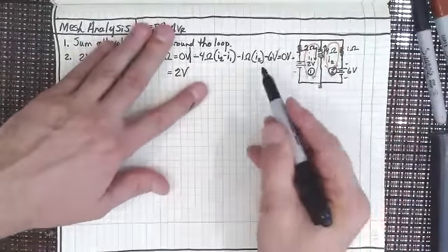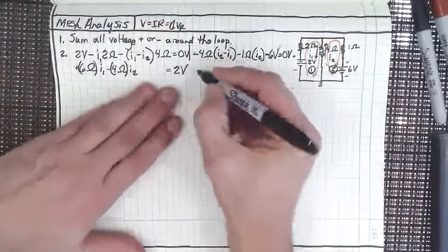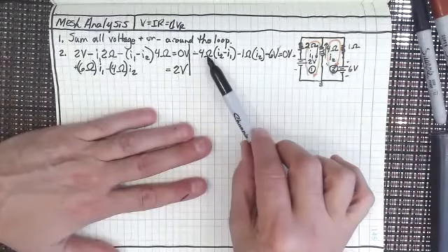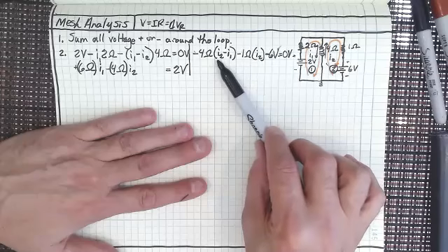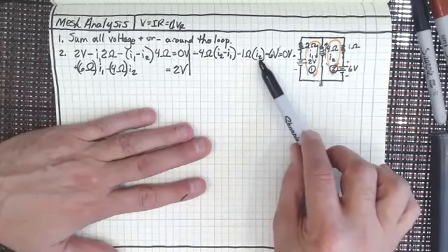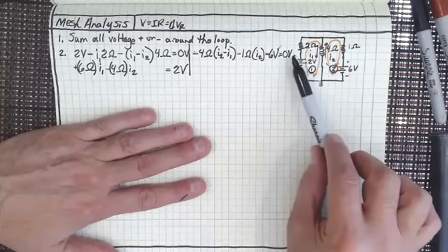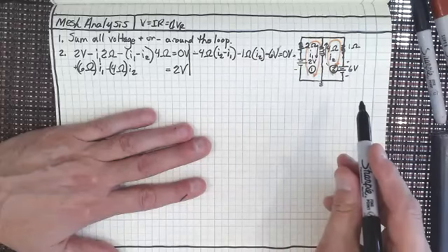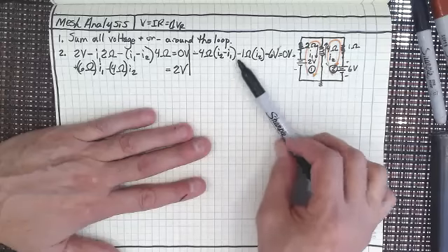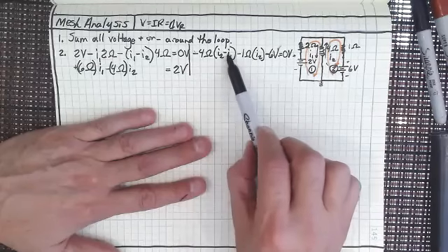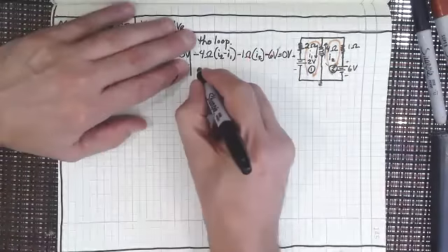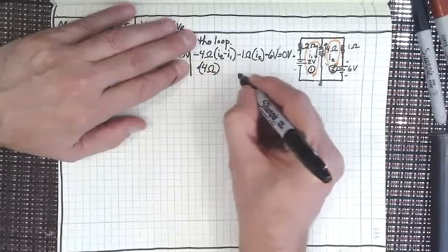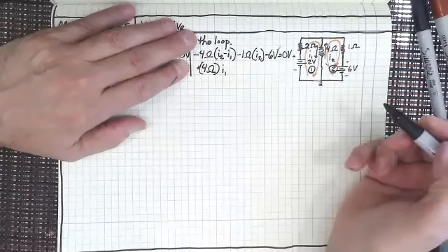If I do the same thing for over here, getting I1, I2 all lined up, let's try this then. So I've got minus 4 ohms I2, minus 1 ohm I2. Why don't we take that over to the other side of the equation, and those minuses will become positives, right? And how about I1? What are we going to have for I1? Now I've got a minus 4 ohms times a minus I1. So doesn't that make it plus 4 ohms, right, times I1.